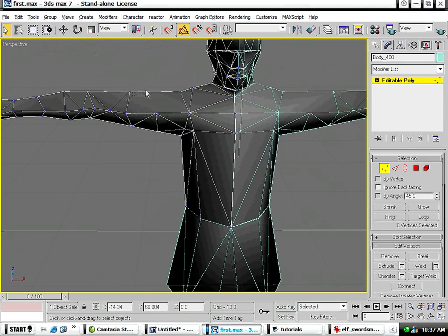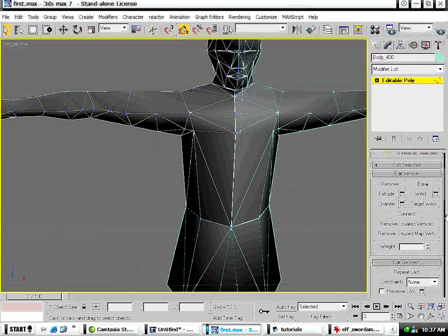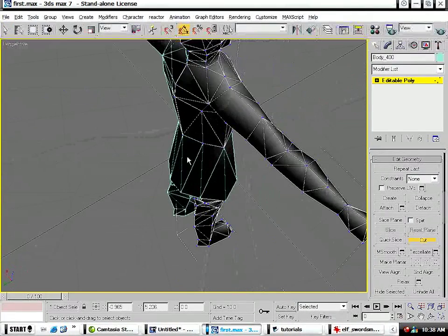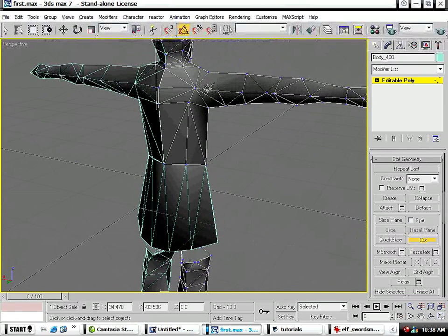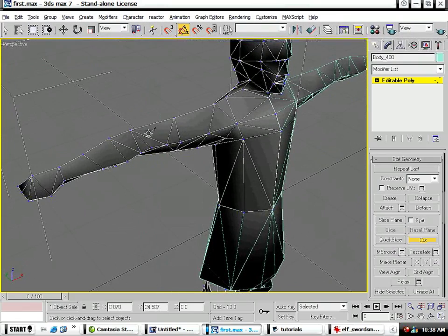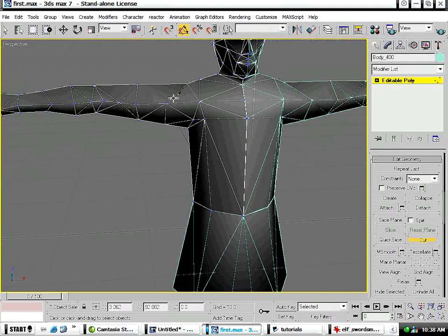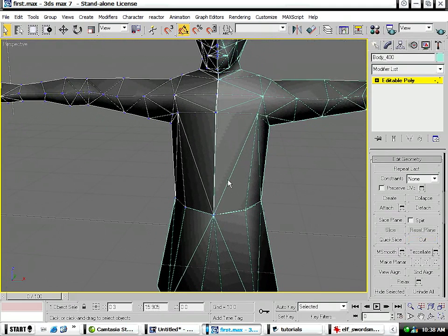Now what you have though is you have a 5-sided polygon. 1, 2, 3, 4, 5. This vertex breaks this one side into 2. So you never want a five-sided. You'd rather go with a 4 and a 3. So you could just select your cut tool. Okay. This is the last way to cut a new geometry. Hit the vertex, and then just hit this one. And the same thing over here. You see how it changes when you're on a flat face, an edge, and a vertex. Okay, and now we've got rid of those polygons.